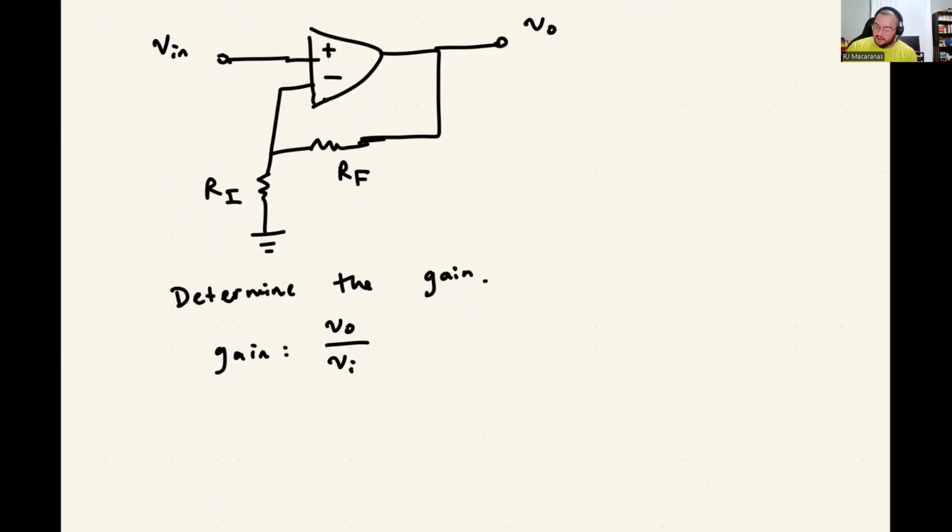So we know that the input voltage, the non-inverting, is equal to the inverting. So I've actually got Vn right here, right? And so if I know that, then I know the voltage right here, and I can actually determine the current that's going through this RF, this feedback resistance here. And so if I define the currents just flowing down to ground like so, and you'll recall that no current is going into the inputs of the op amp there.